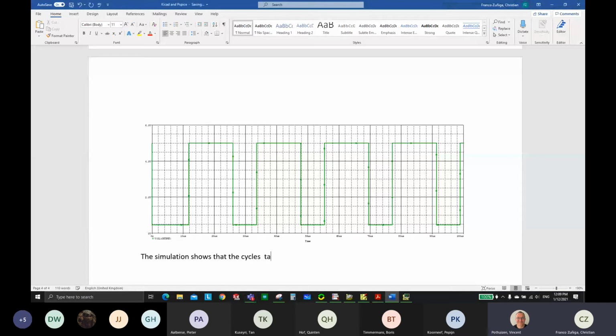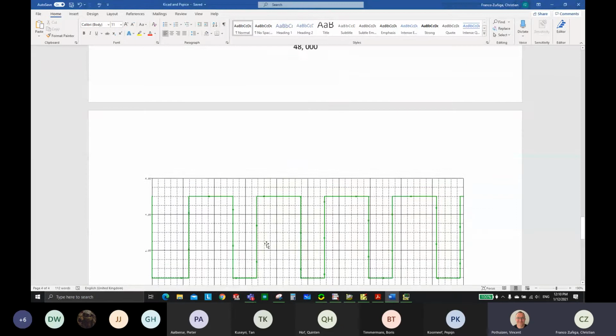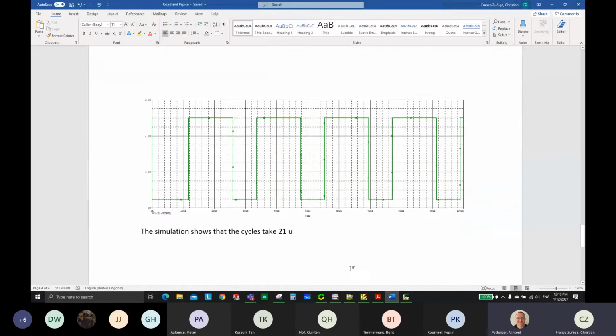And if the delay time for digital write high and then after digital write low are exactly the same, then the duty cycle is 50%. The signal is the same, say it's 10 microseconds high and also 10 microseconds low, then they say the duty cycle is 50%. So we can check later on in this circuit how we can play around with changing some values to change the duty cycle. That's extra information.